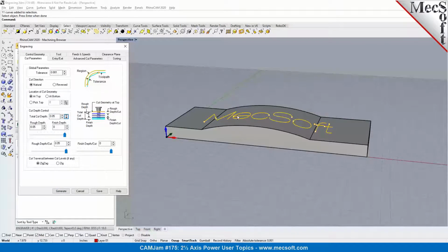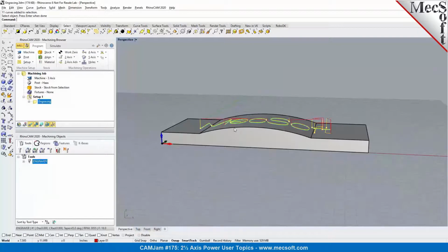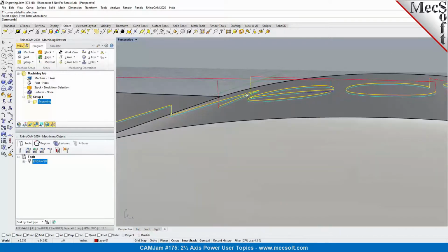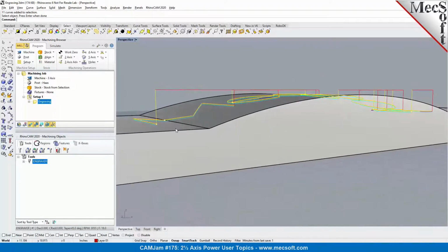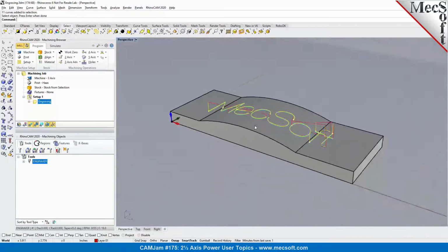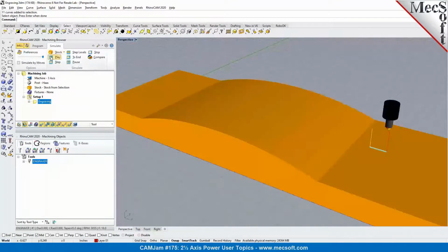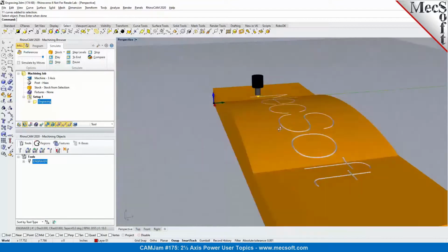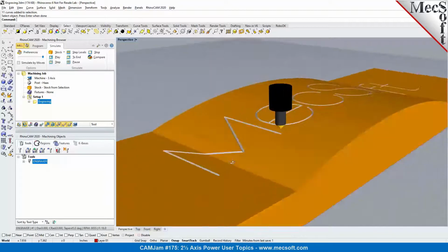So it's going to maintain the same depth across the 3D curve geometry that you have here on engraving. So as you can see, the toolpath stays on the drive geometry and also maintains the XYZ varies as it follows the 3D curve geometry. So it's not resulting in a planar toolpath. It does follow along the 3D geometry. So this could be one of the very nice use cases for engraving along sculpted surfaces as well.